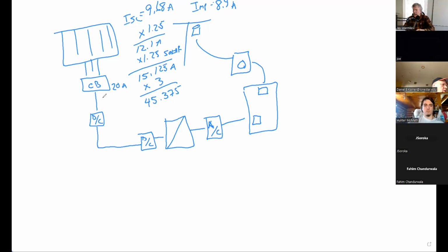Yeah, and that's one of the points I wanted to get to is the table is broken into columns, and the ampacity rating of each wire is different depending on the type of wire you're using. So in column 1, we have TW or UF. And if we use 8 gauge, it's rated for 40 amps.